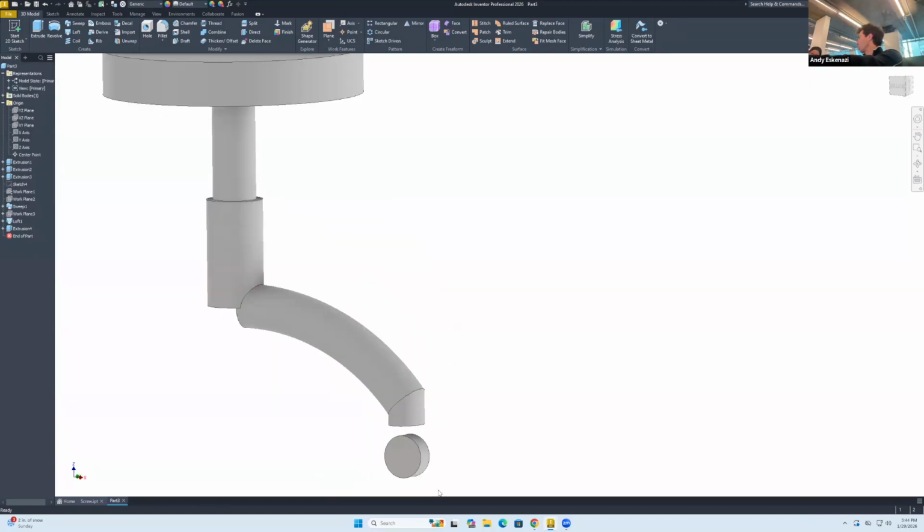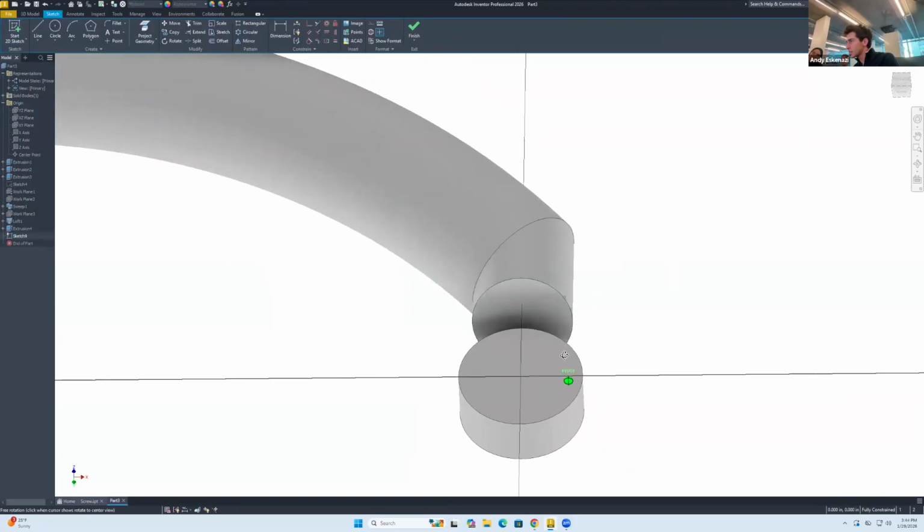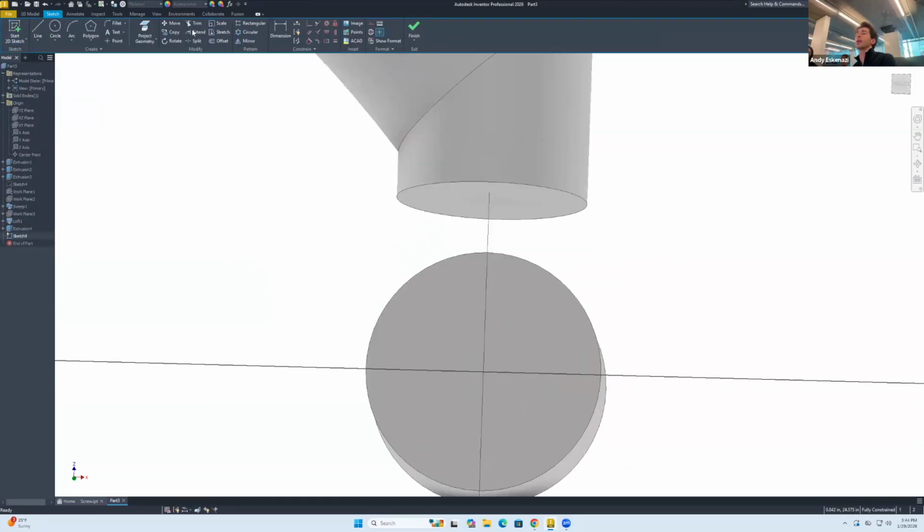You see that that's floating in there. Normally you shouldn't do that, but it's okay. I'll do here a sketch on that face. And what we're gonna do is the following thing. We are gonna go here to project geometry, that line. So that brings us here. And I'm gonna draw a little bracket that goes like that.